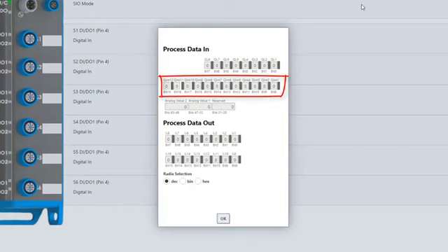QINT1 through QINT12 are the states of each input or output on the 6 main M12 ports. Each bit has a bar next to it that will be gray if the signal is logic 0 and lights up orange if the signal is logic 1. Note that the M12 power port has two discrete outputs, but these are not transmitted in the IO-Link process data frame since they also occupy the M12 power port.